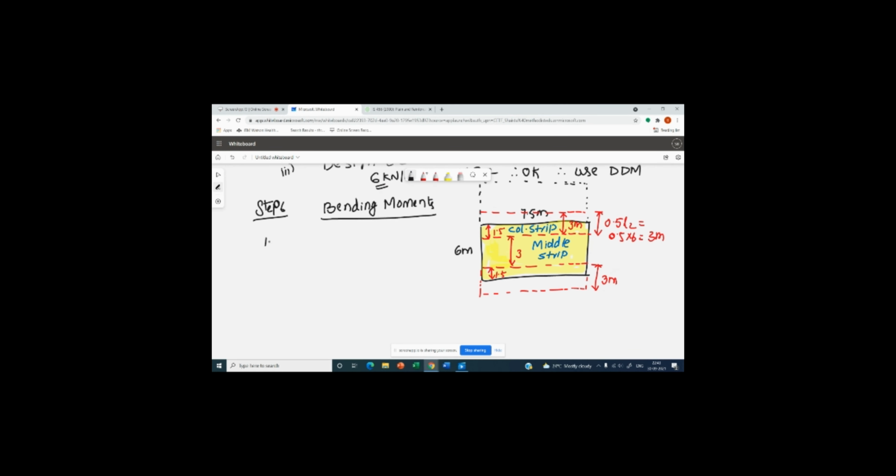So let us do that part here, on the drawing I have shown you. Let us do it. So width of strip. Now for this also the clause is there, 31.1.1, the first clause of the first subpart of 31 clause. So we have to do it as per 31.1.1. As I said, we have got two spans. One is along 7.5 meters, the other is along 6 meters.